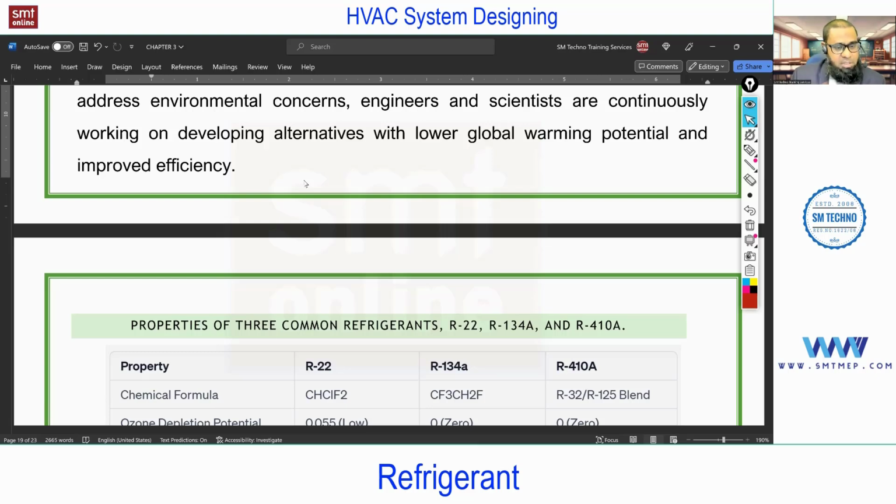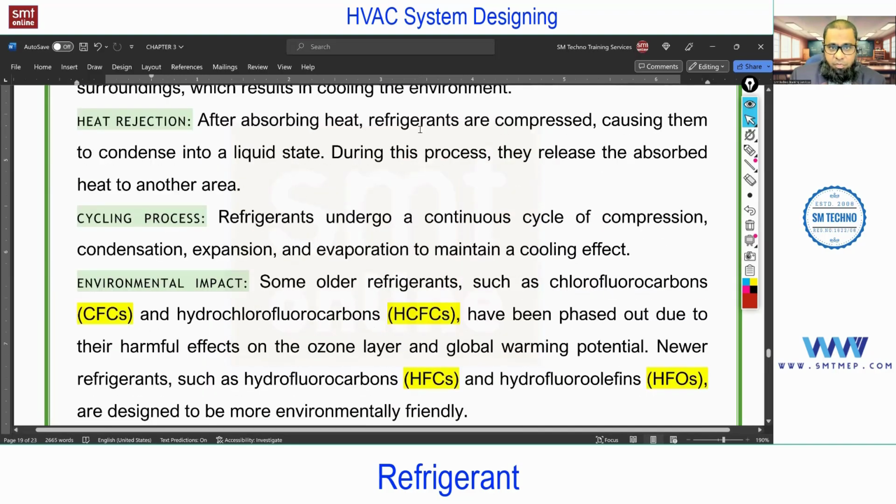But the designing of the pipe, except VRF or other systems, I'm talking about the copper pipe, does not belong to the HVAC design engineer. It belongs to HVAC if you're working on the manufacturing side as an application engineer; you are going to be involved in that. So now, with this information, we are ready to deal with the vapor compression cycle, which is a base for the different air conditioning systems. I can relate this to chapter 5.